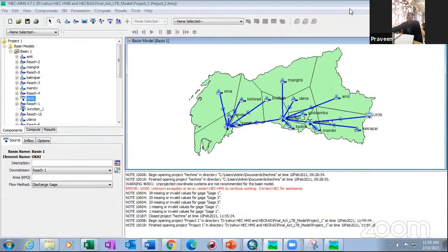Ultimately we are defining the curve number, right? So the curve number or any other parameters will be very difficult to make dynamic. In that case, better divide your 20 years of data into 5-year periods and do the calibration for each 5 years, and then start simulating whatever analysis you want to do. I hope I answered Santosh sir's question. The conclusion is that for 20 years, if there are appreciable changes, then definitely you have to divide the models into different time stages.